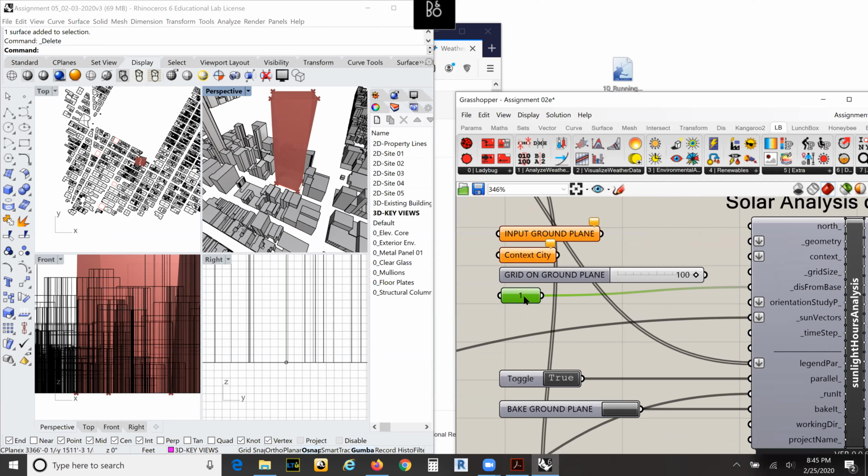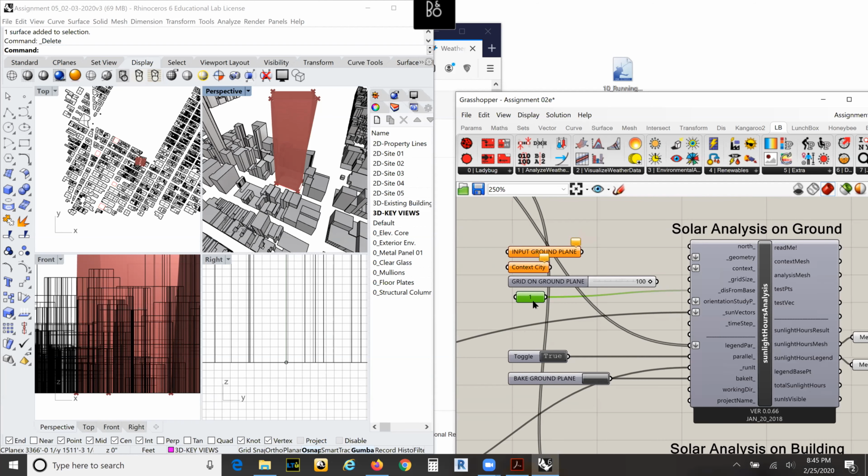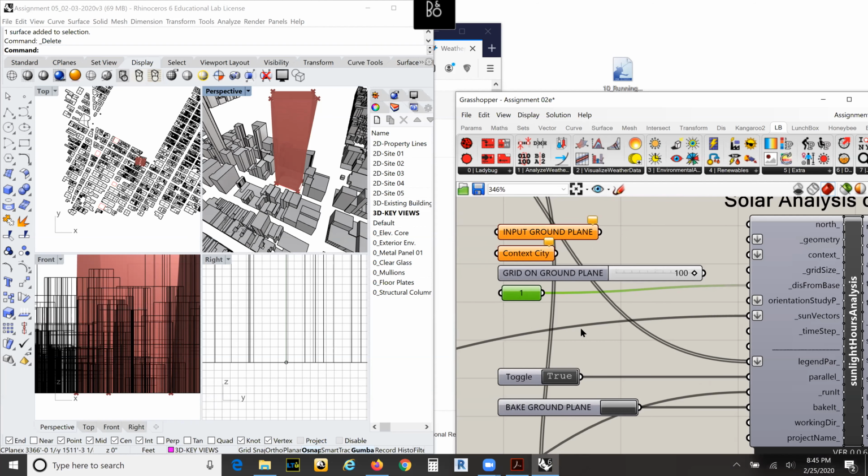either needs to get larger or smaller. Now in this case, when I was first writing this script, I usually have this number very small. Like I used in the previous assignments, it was 0.01. That usually is my go-to number. It's small, it works. But in this case, that was too small, and I was getting some very weird results. So I had to increase this number to get the results that were correct. So just keep in mind, if you are getting some weird results and you're not sure, and your meshes are unified, it might be because of this.